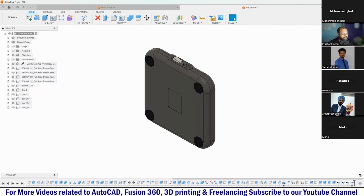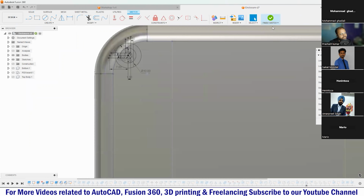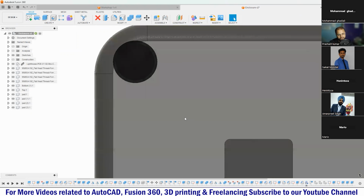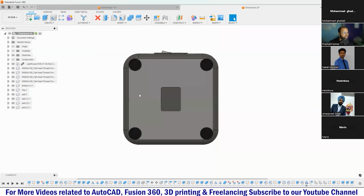If you want to make an edit at any particular step that I did, for example, if you want to modify this sketch, you can just come to this history feature and double click, and you will be able to make edits inside your sketch. The moment you are done, you can just finish and everything will get updated afterwards. So that's why I call this tool very strong, guys, very strong, right?